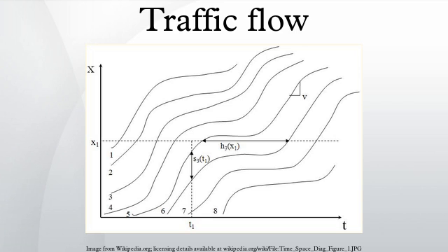Suppose there is a freeway, 0, and an alternative route, 1, onto which users can be diverted via an off-ramp. The operator knows the total arrival rate, A(t), the capacity of the freeway, μ0, and the capacity of the alternative route, μ1. From time T0, when the freeway is congested, some of the users start moving to the alternative route. However, at T1, the alternative route is also at full capacity. Now the operator decides the number of vehicles, N, which use the alternative route.